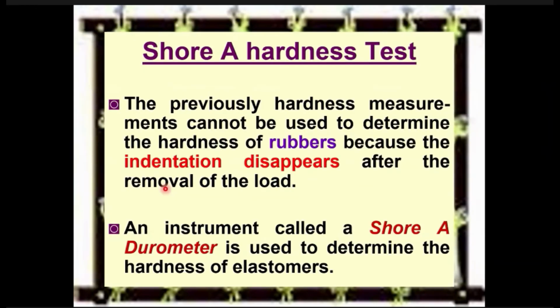Another similar method is the Shore hardness tester. This comes with a meter or scale which is called a durometer, scaled from 0 to 100. How this works, again, this system comes with an indenter which can penetrate into rubber materials, and the durometer tells us a reading from 0 to 100.